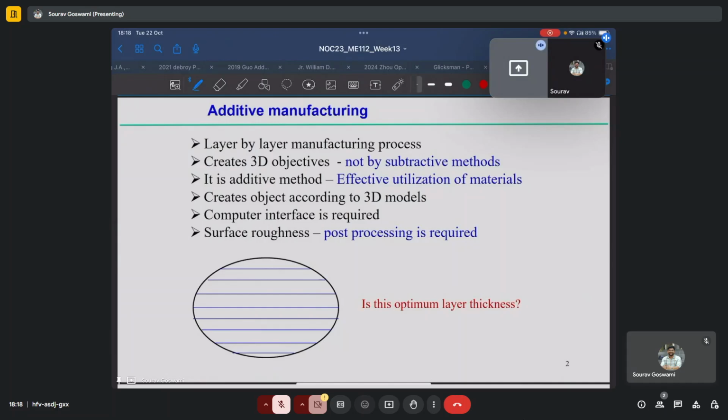However, as we already saw, there are certain additive processes which are inherently hybrid in nature. And when we say hybrid, what we really mean is that they will have both additive steps and at least one subtractive step, such as all sheet additive manufacturing processes, also commonly known as laminated object manufacturing, are inherently of a hybrid type.